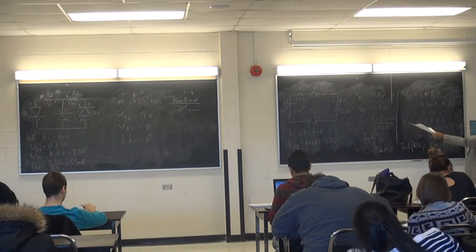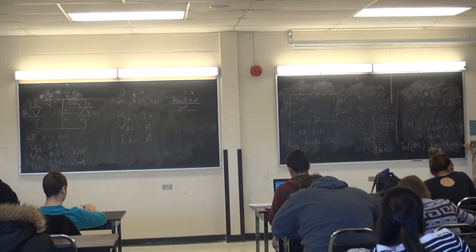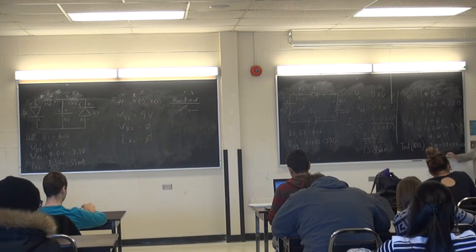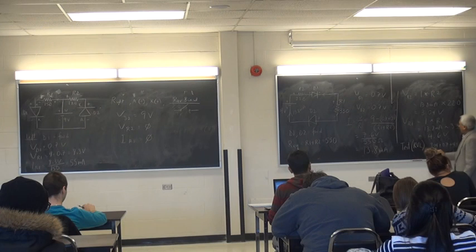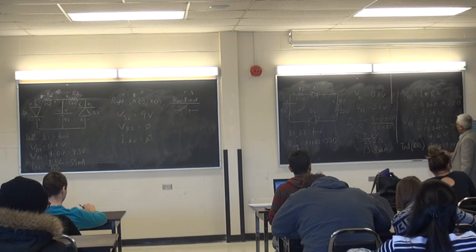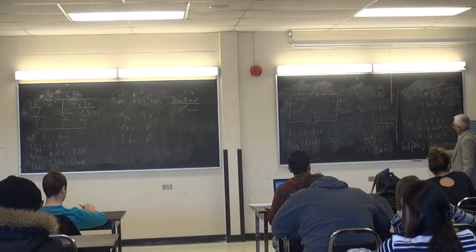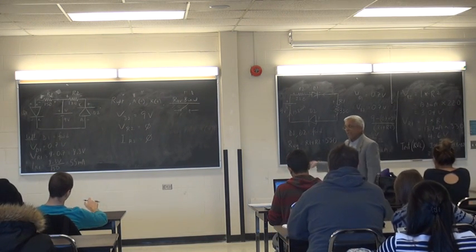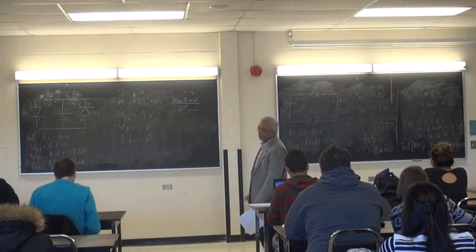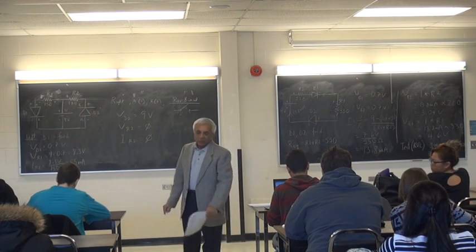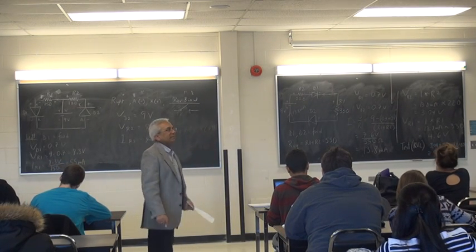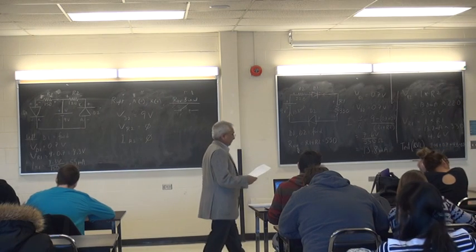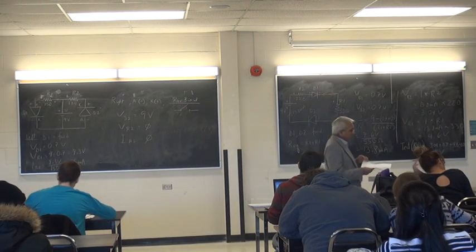And the voltage at D2, 0.7. What do we get? 9.0. 9 volts. Okay, all the voltage drops should equal the voltage rise, which is the supply voltage. Make sense? So that's number 8.